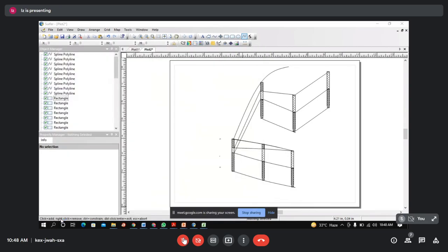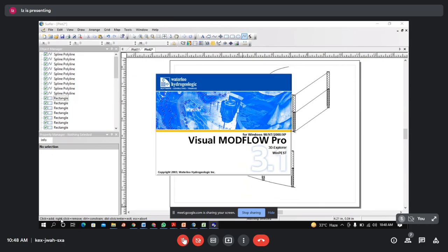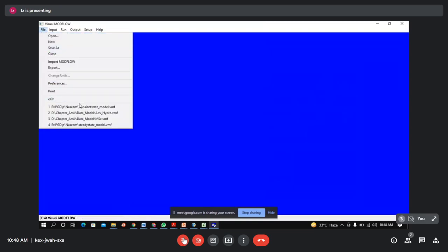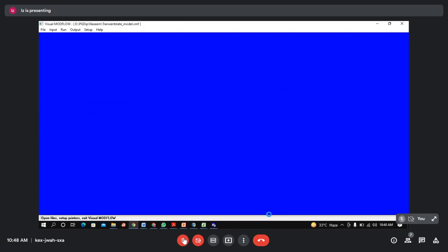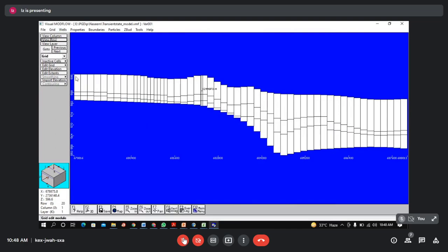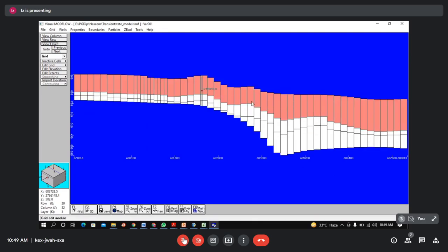Okay, so this is a very important exercise in a manner that once you go for the big things like groundwater modeling, in groundwater modeling you need to conceptualize the area. So conceptualization means what, I'll tell you. For example, you need to have the raster layer of first elevation and the bottom of it. See, this is the first layer, this is the second layer, and this is the third layer, right? So you need to have the top and bottom of each layer. In that manner, this is very important. Okay, that is the applied aspect of that exercise.